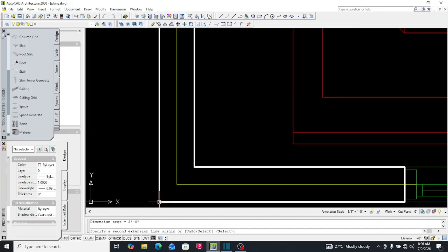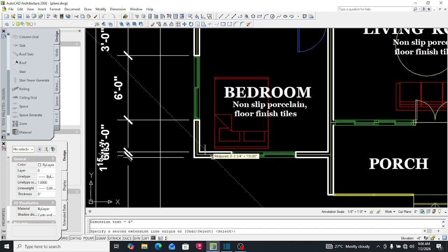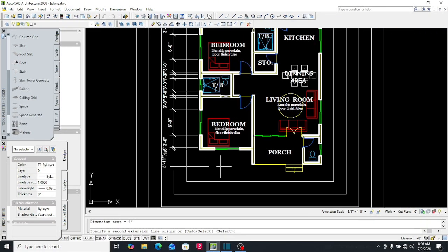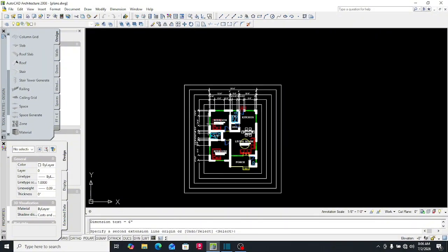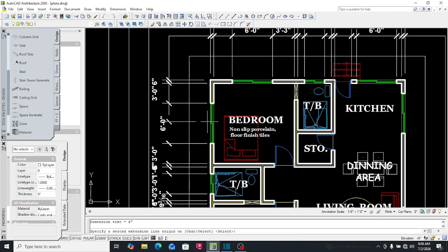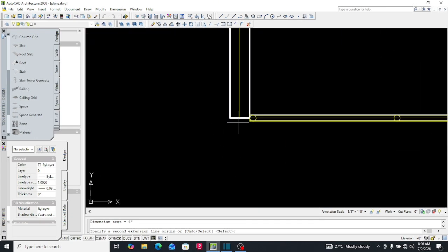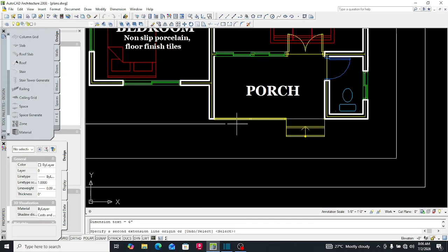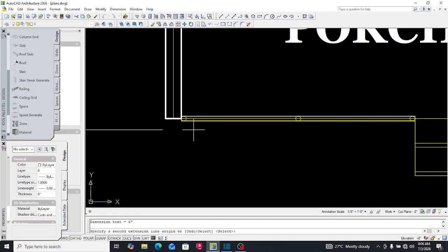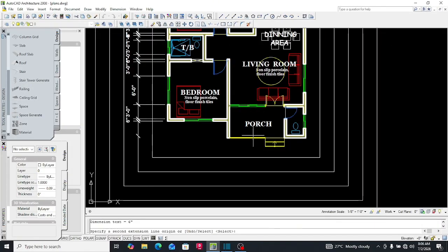On the left side of the building, or the left elevation, we are not having any door here. It's just the windows, so we measure the windows. Then again, this is a porch. Please, when you come here, don't pick this line, because you are looking for the block.